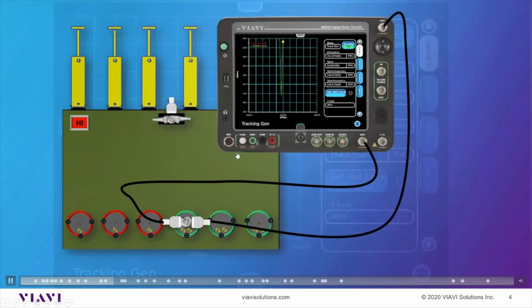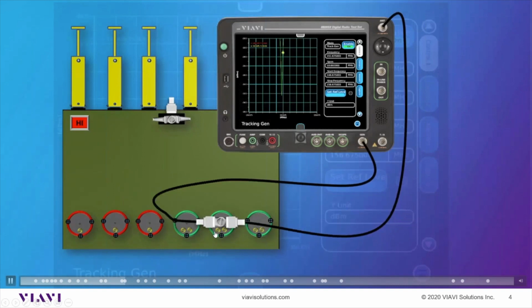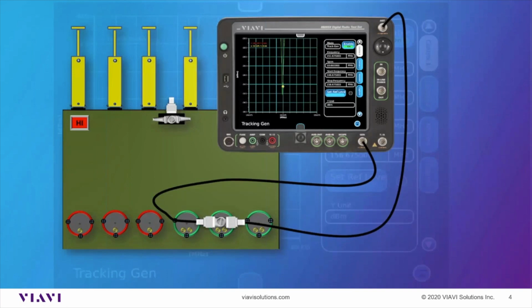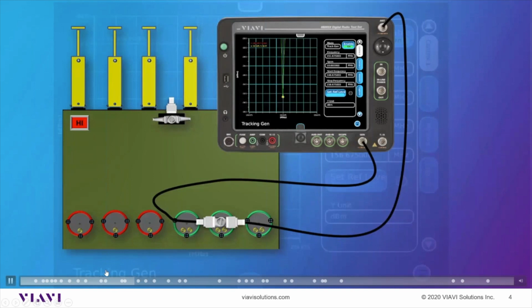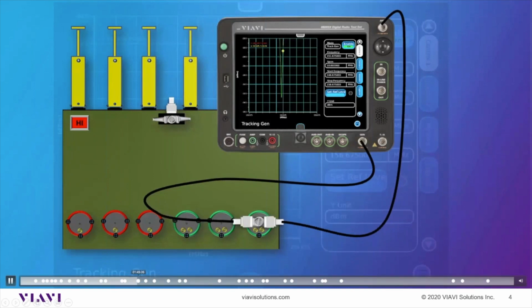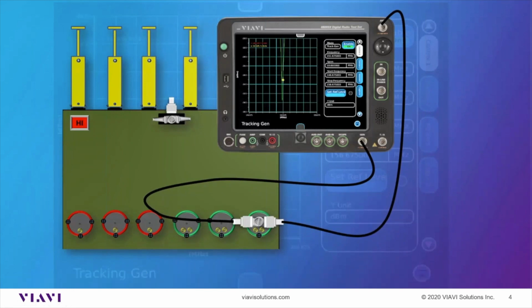So now I'm changing my frequency to the high pass notch. And on the low pass resonators down here, you notice we have 2 caps. They are interactive, and you'll have to go back and forth to give you the maximum depth on that high pass notch. And then we'll peak our last, or get our depth on our last notch.